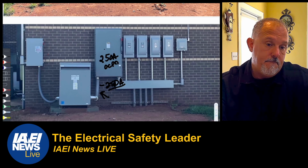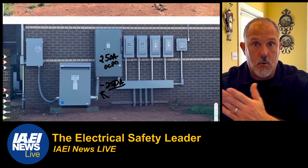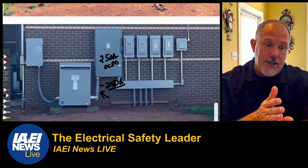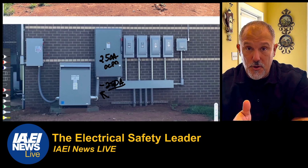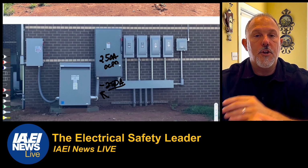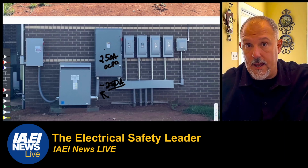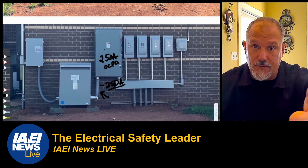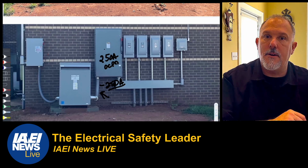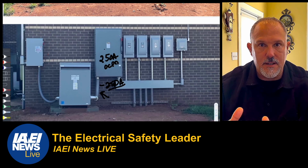Now let's take a look at the other requirements. If those transformer conductors did not meet the outside requirements, now we're inside the structure, and I'm into different rules. 240.21(C)(2) says transformer secondary conductors not over 10 foot long. Remember, these transformer secondary conductors are not protected at the source. We already know the only way the primary overcurrent device can protect those conductors is if you have a delta-delta transformer, or a single phase 2-wire transformer, and you transpose that conductor ampacity to the primary and the primary overcurrent device protects that conductor, which is not the case in most of the applications that we install.